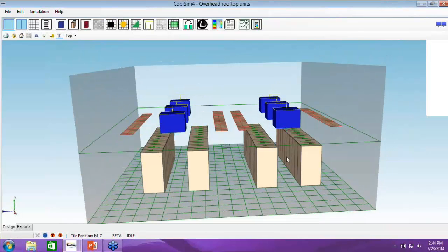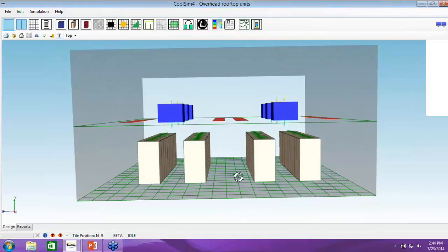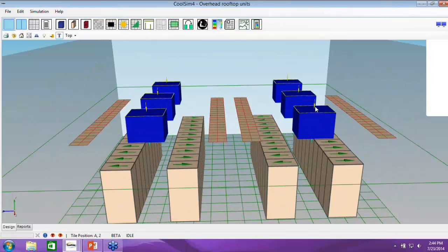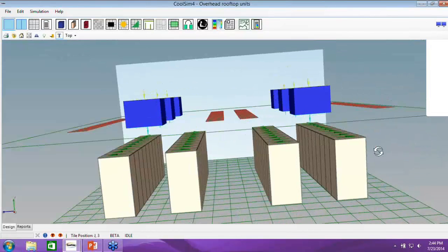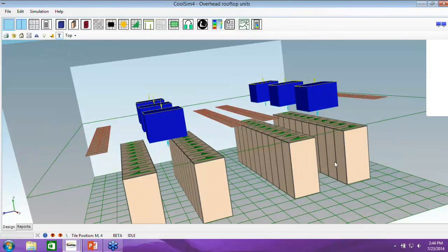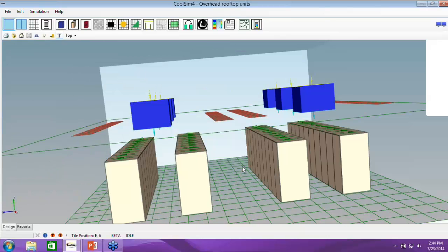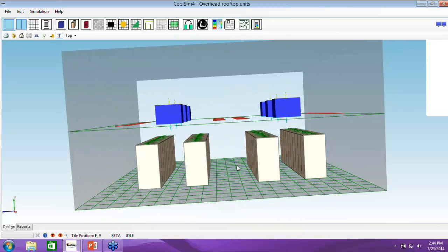And what we have here is a model of what they often call rooftop units. They sit up on top, and they dump air down into, again, sort of a bathtub. It's kind of a bathtub effect, right? You can put end caps on these things, and it would be like a bathtub filling up with cold air. This also could be used to model an air side economizer. So the idea would be the air comes out, goes up through these grills and into the atmosphere. This would be the atmosphere, and from another source you get cold air coming in. That source would be outside air.